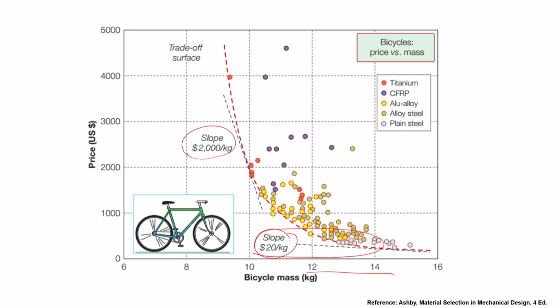So, you can see that titanium becomes an important choice here, whereas here you can see the plain steel becomes an important choice, because this side of the Pareto front is less mass sensitive, but this side is very highly mass sensitive. So, that is the way, by the use of value function, if you know the exchange constants, okay, you need a bit of experience to do it, you should be able to actually choose the material corresponding to compound objectives. So, not just only one objective, but there are multiple objectives. If there are more than two, let us say 3, 4, 5, then this curve will become multidimensional in nature. That is the way we can solve the problem. Thank you.